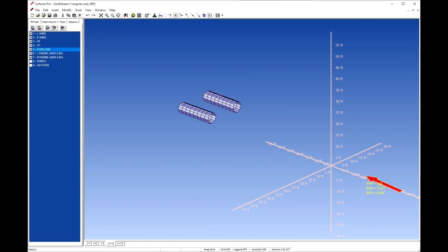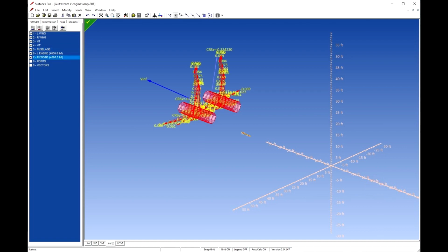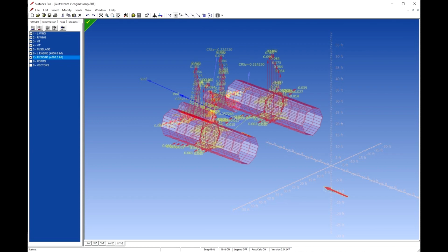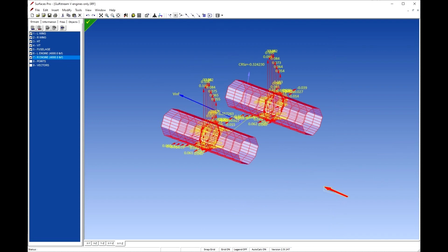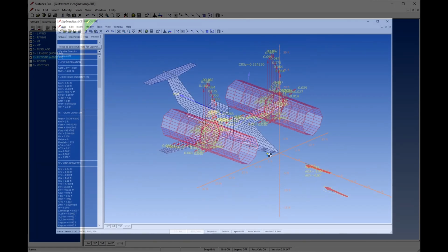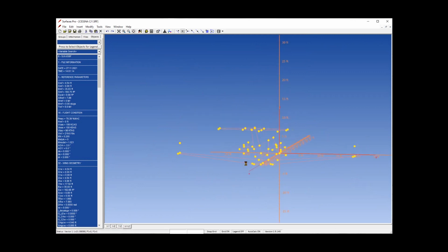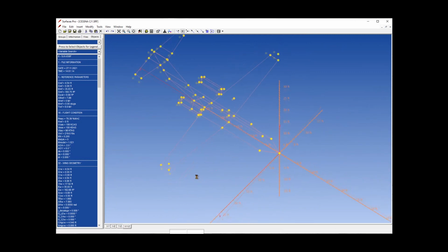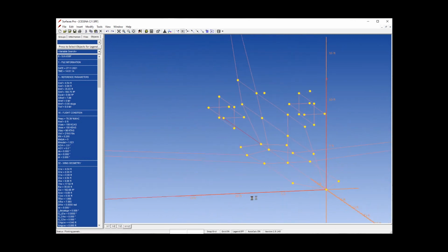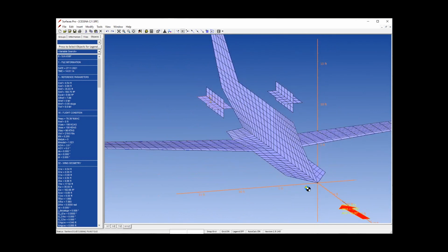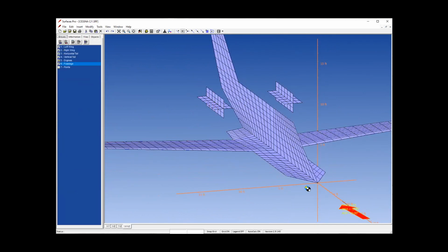However, the orientation of the surfaces is critical to proper implementation. When the nacelle is at an angle of attack, all its panels should be generating an upward pointed force. When the nacelle is at a non-zero angle of yaw, its panels should develop sideways force that is properly aligned with the airstream. Therefore, making a hoop nacelle is a little bit tricky. Surfaces now comes with a new tool to make this easier. It allows circular hoops to be automatically generated.